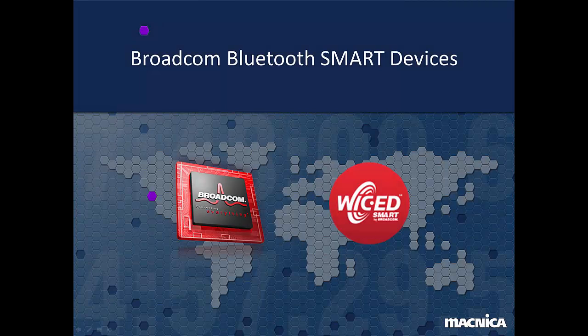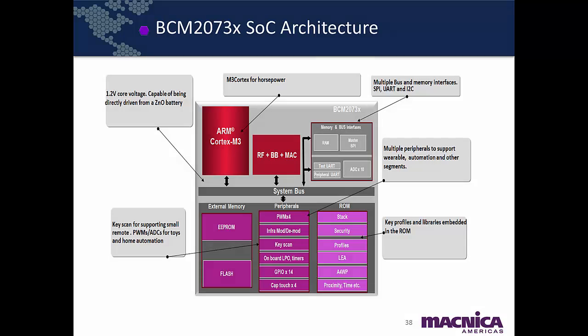Okay, enough about technology fundamentals, specs, and protocols. Let's bite into some meat here and discuss real Bluetooth Smart devices. Broadcom has several options to fit your needs. First off, I'll detail the Broadcom 2073X family of Bluetooth Smart SoC devices. This is a true system-on-a-chip device that has a processor and peripherals, memories, and an RF section, all accessing a common system interconnect bus.